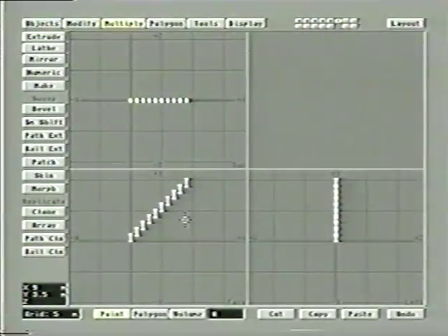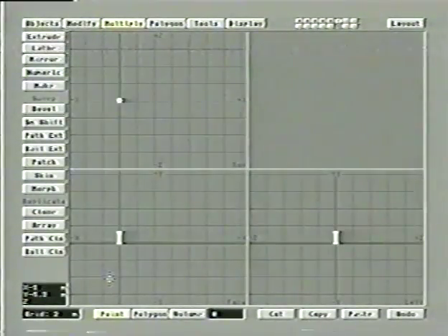Now, one thing that's often handy, you can see the idea of it using with offsets, is that you can clone things by using rotate. And this, for instance, is very handy if you're creating something like the spokes on the wheel of a bicycle. What you're doing now is you're not really offsetting it, but you're taking each one and giving it a rotation. And so here's what we'll do to do that. We'll undo what we just did.